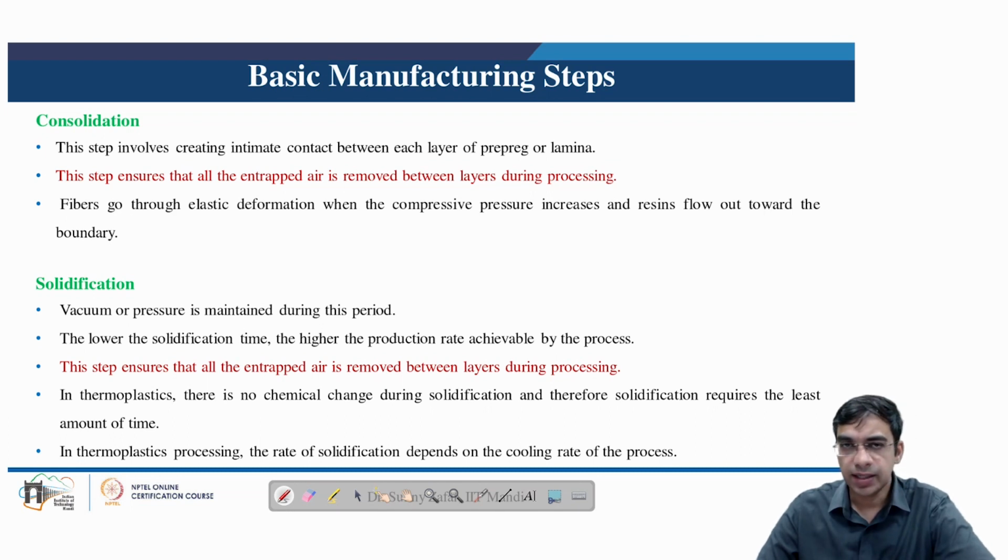Solidification is the last step in the general outlay of the manufacturing process. In the solidification step, use of vacuum or positive pressure is maintained. The lower the solidification time, the higher the production rate achieved by the respective manufacturing process. This step ensures that all entrapped air is removed between the layers during processing. In thermoplastics, as we know, there is no chemical change during solidification, so their solidification requires the least amount of time. In thermoplastic processing, the rate of solidification is also dependent on the cooling rate of the process.